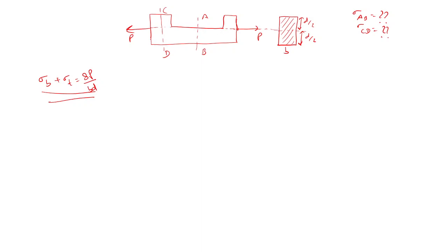So we can individually add the stress components, because both are normal stresses, right? Tensile stress and bending stress both are normal stress, while shear stress like torsion will come under shear stresses. So normal stresses we can add. In bending, in one direction it would be tensile and in the other direction compressive, and the magnitude would be the same, with the variation this way. Let's suppose this is the cross section; this would be the neutral axis line.